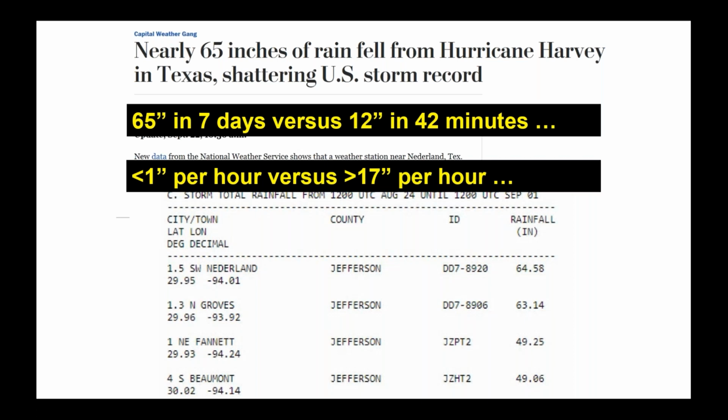And for dams with smaller drainage areas, and most of the NRCS dams are between 2 to 10 square miles, some of them go up to about 20 square miles, but we're looking at a time of concentration, the time from when a drop of rainfall hits the farthest part of the watershed to when that drop of water reaches the reservoir.